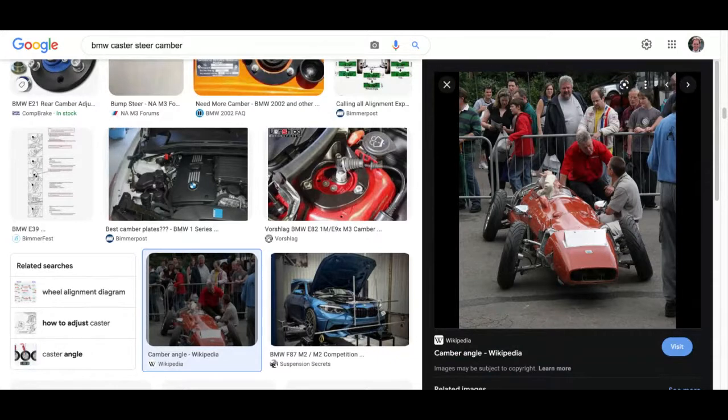The benefit was that you've got large amounts of lateral force being generated. In a straight line they were counteracted by each other, but in the corners, when there's most load on one side, you've got additional cornering force like you would on a motorcycle. So that's a particular example of a car with a ridiculous camber. Anyway, let's press stop.